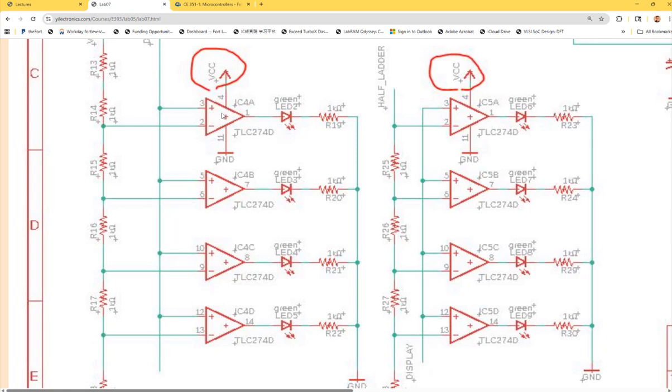So when you are placing these op-amps, if you place them in a certain sequence, don't cancel it and replace it. Just directly after you grab that component, place it 1, 2, 3, 4. Don't stop, non-stop, okay? In that case, you will be able to place these 4, A, B, C, and D, from the same chip into the schematic. Even though this seems like there are 4 different devices, if you jump to the layout, they are actually the same chip, just one chip. Then after the 4th one, if you keep placing, it will start from IC5. This is handled by Eagle automatically. It's a really nice feature of it.